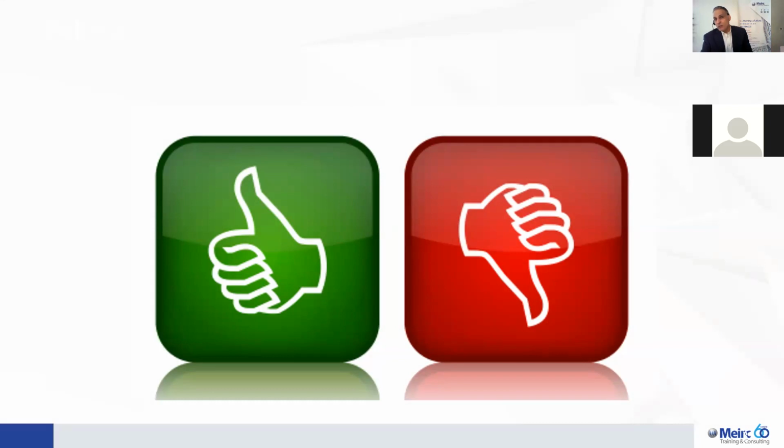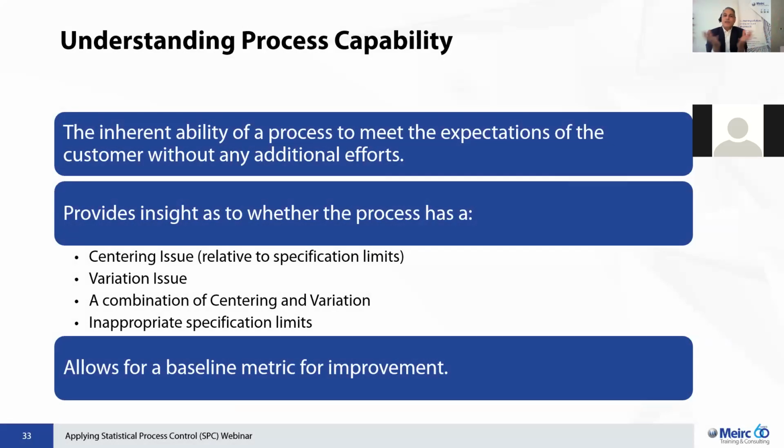Now, professionals have designed certain indices to tell me whether an index of 1 or 1.2 or 1.33 or 2, and they called it the CPK, process capability indices. For people who are familiar with Six Sigma, the Six Sigma metric came as a result of the process capability indices, the CPK, or defects per million opportunities. So when we say a process capability of CPK 2, which is equivalent to 6 Sigma, it means that a process really has very good quality levels in achieving the customer requirements.